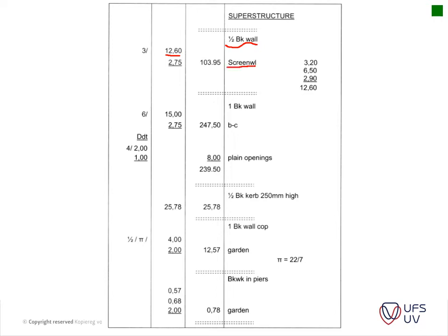So you divide your brickwork into different sections, so you group them again. You've got half brick walls, which is 110mm brick walls. So you've measured 12.6 meters of them. You measured that they're 2.7 meters high, and there were 3 of those sections that were the same height. Okay, so that is basically how it's measured.